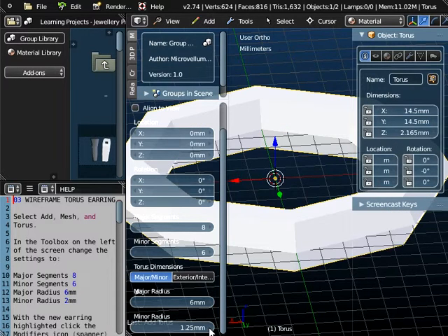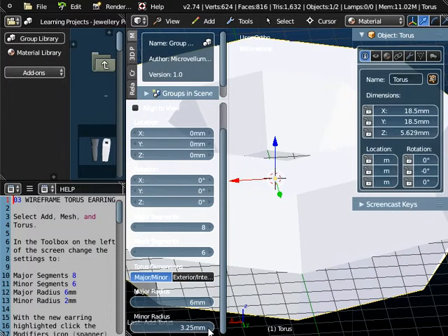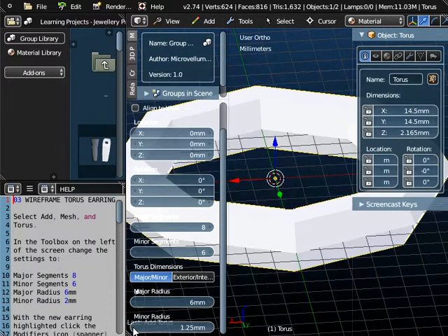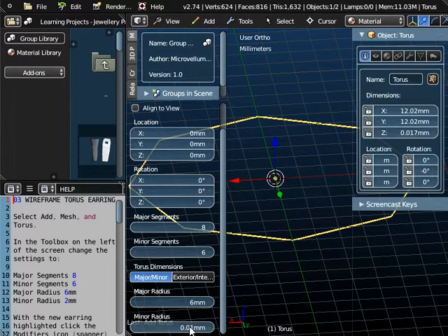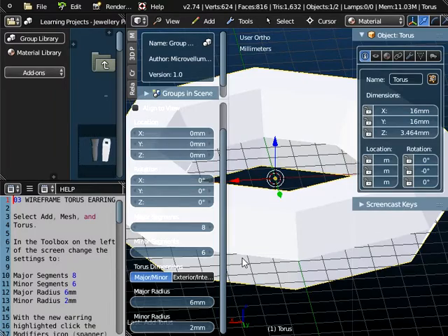All this does is thicken up the torus. Now we want a value of 2 millimeters. Now we need to be a little bit careful here. If we type in 2, it won't work. We go really thin, and you can see it says 0.01 millimeter. We need to do 2 mm. So if things go strange, just add the units, and there it is.